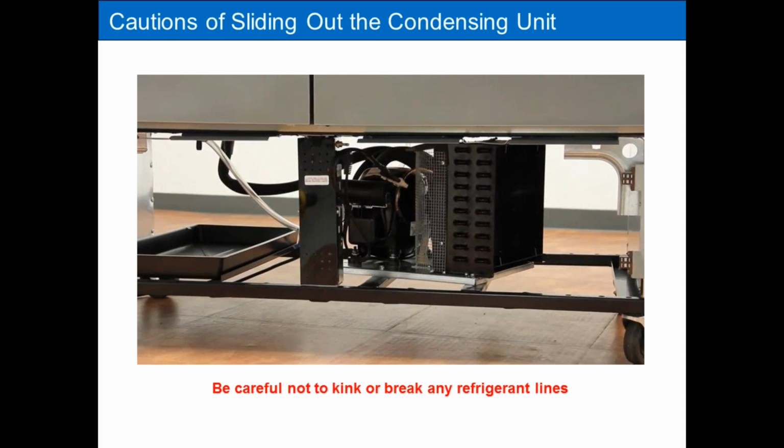The next day they called up and said the cooler stopped working that night. Unfortunately, I couldn't get there until the following day, so it was 2 days. The unit was down, and it had dumped all the refrigerant out, and the compressor failed because it was an older compressor running without any refrigerant for 2 days. They did not unplug it, and the compressor failed. So I had to change the compressor and fix the leak, something that maybe could have been avoided by how I pushed it back in.